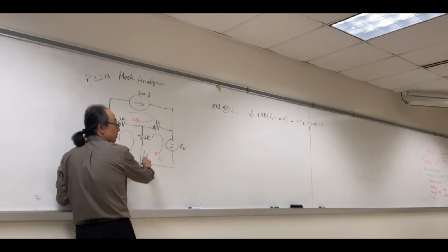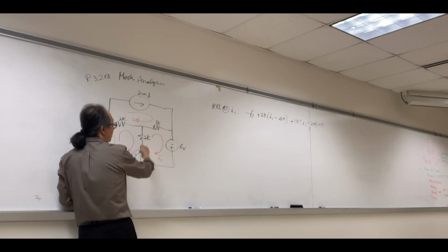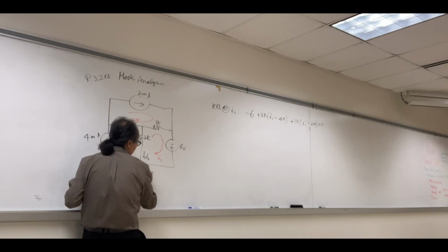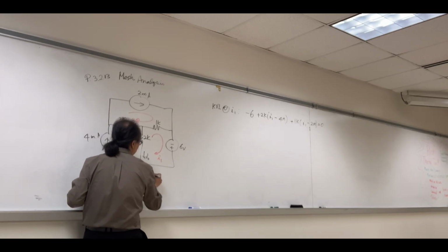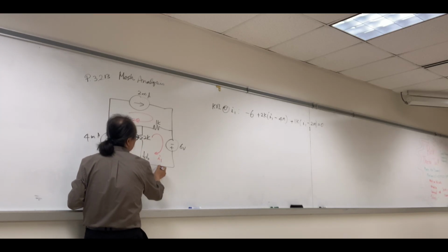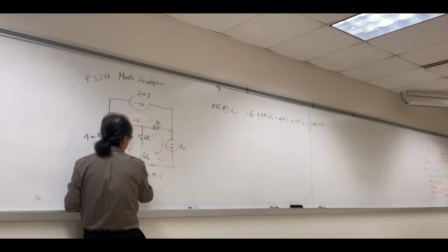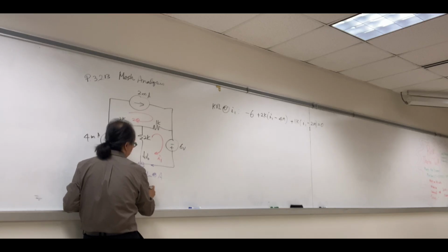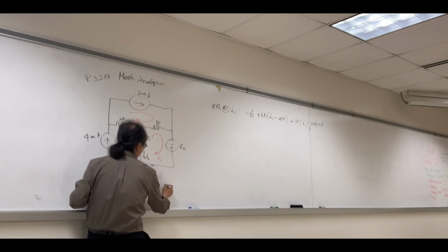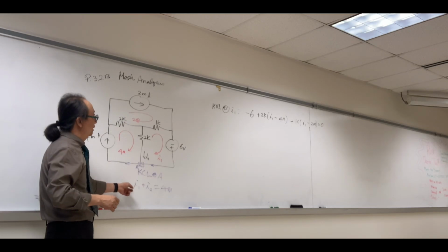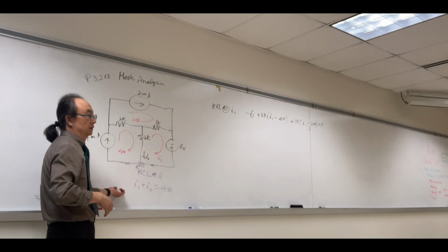But I sub 0 is not the mesh current. That's the current going through this 2 kilo ohm. We'll eventually do KCL at A. This is entering, this is entering, this is leaving. So entering is I sub 1, entering is I sub 0, equals leaving, which is 4 milli. We end up getting two equations with two unknowns.